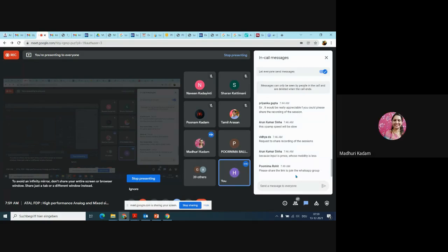At 32 the range will be 2 to 4 around. That is the intrinsic gain I'm talking about. And at 65 nanometer, around 25. This is just a rule of thumb. It changes from technology to technology, but you can get approximately those numbers.